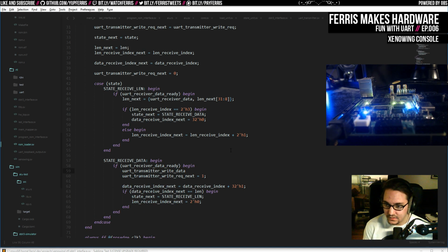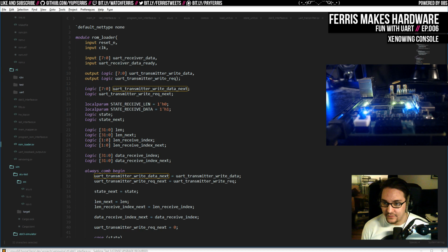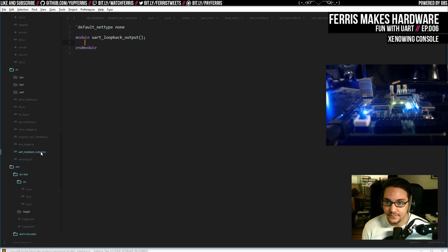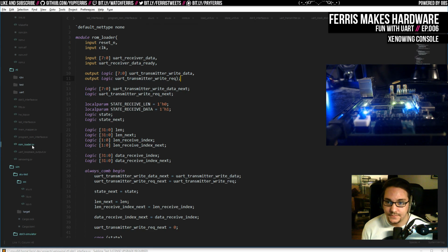And the write data is going to be our receive data. So on the cycle following this, this will just push it out to whatever this interface is. We're going to hook it up to a FIFO, and then another unit is going to pull off the other end of the FIFO that's going to actually loop back to our transmitter. That's all that is.